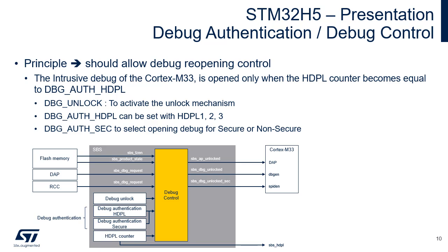The outputs of the debug control unit indicate whether debug is locked, debug is only enabled for a non-secure state, or debug is enabled for both non-secure and secure states.